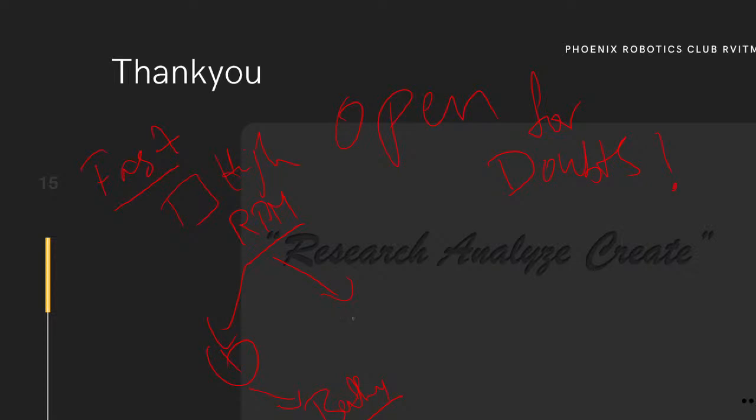And the other thing is the sensors should be sensitive to change if it is moving so fast. Suppose there is suddenly a straight 90 degree turn, and in our competition they gave a turn like this, where the robot has to move here and turn in this direction. If the robot is moving so fast, the sensors should identify this turn and it has to respond immediately, otherwise it will move out of the path.